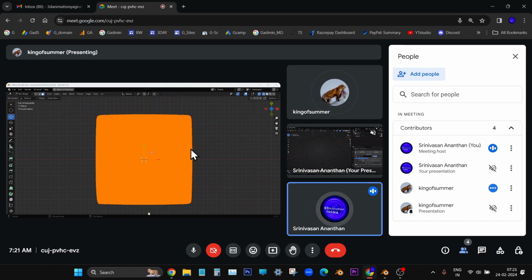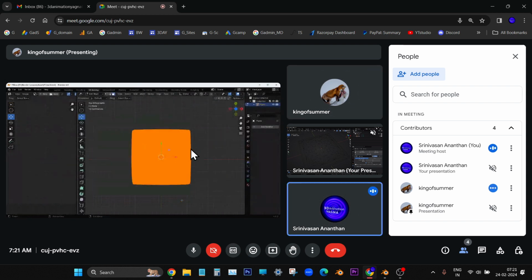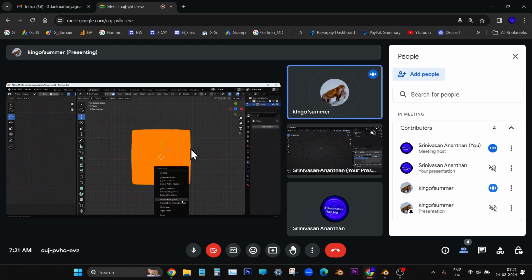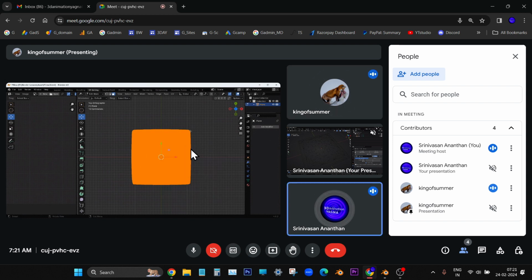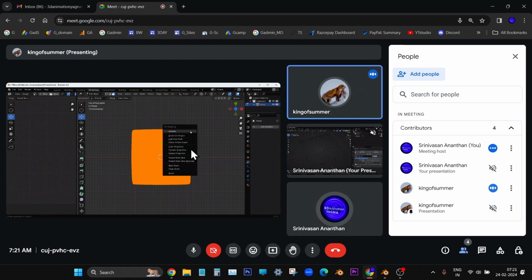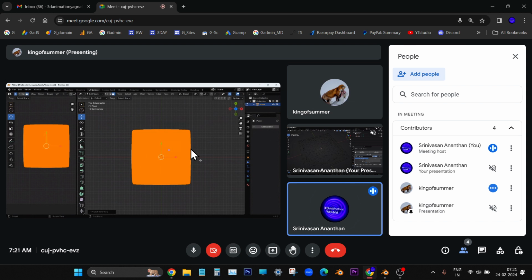Now press Ctrl Space. Now press U on the keyboard. You are in top orthographic view now. Choose, wait, yeah, that menu should be there. You press U and you see Project from View. Yeah, choose it. Now you see what has happened. Just listen, you don't have to do anything.